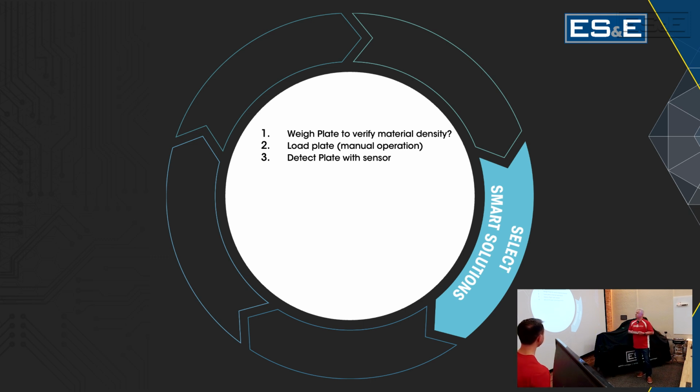That sounds good. Once the photo eye detects the plate, the plate will then take off down the conveyor. Then it'll pass under your automated brush to clean it off. Okay. Get all the dust and particles off of it. Then once the plate is clean, it'll go under your barcode reader. It'll stop in the same place every time. We'll be using this servo. We'll make sure it's in the correct spot every time. Then when it comes to a stop, we'll take a picture of the barcode, verify the data, send it back